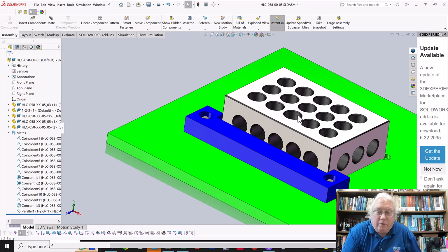And then when you locate those holes, all of the dimensions that locate those holes are going to come from those datums, and they're going to be basic dimensions. And once we locate those holes using those basic dimensions, then we're going to add a feature control frame to define the positional tolerance of those holes. So that's what we'll do in the other video.